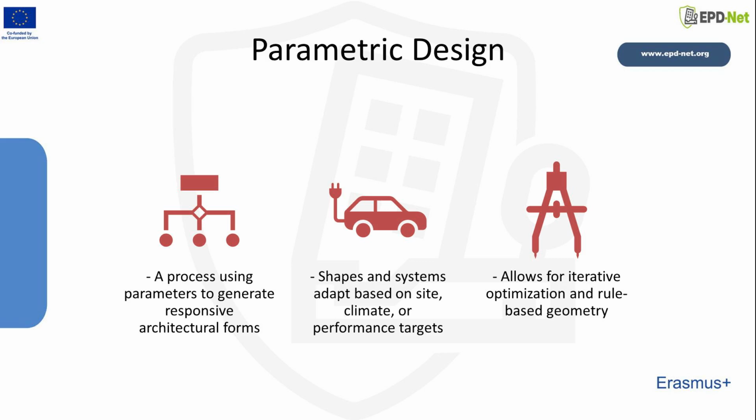Parametric design is an approach that uses algorithmic thinking to solve design problems by translating the relationships between internal and external variables into formal parameters. This design process utilizes parameterized digital models where changing an input value automatically updates the geometry and lifecycle scenarios, generating responsive architectural forms that are intrinsically constrained by defining equations and multi-step algorithms.